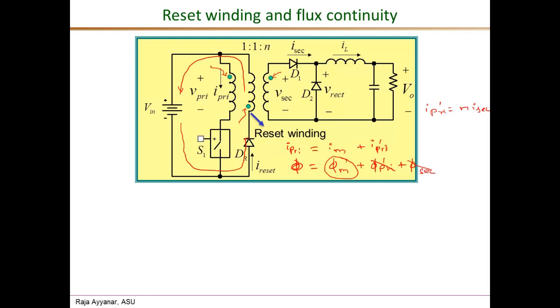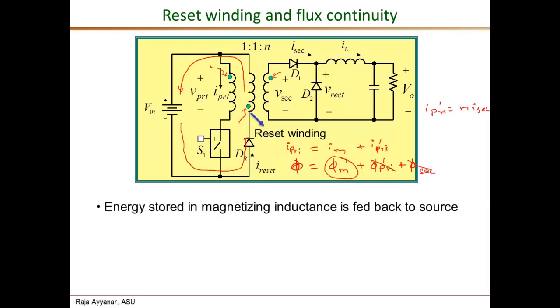So what we see is that the complete energy stored in the magnetizing inductance is fed back into the source during the off interval. We'll see that during part of the off interval.